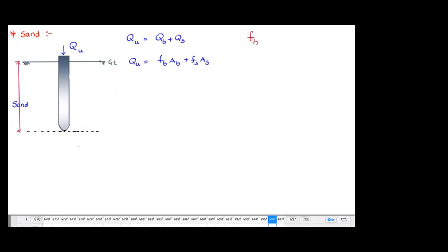You know that in the case of sands, the bearing capacity is simply, I told you, sigma V dash into Nq. If you forget about that, from the Terzaghi equation, there are three effects: cohesion effect, width effect, depth effect. Width effect you neglect. If it is a sand, cohesion effect also neglect. Then what else remaining? Depth effect, which is nothing but sigma V dash into Nq.